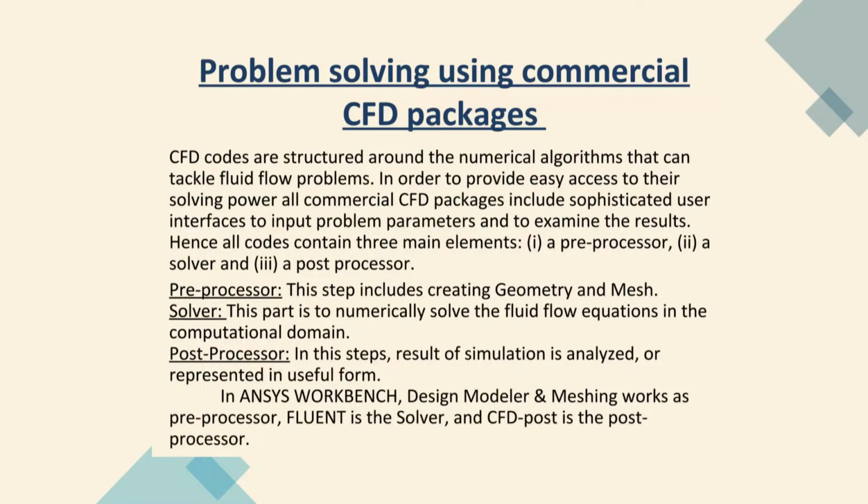The preprocessor step includes creating the geometry and the mesh. You can create the geometry and mesh somewhere else, export the mesh, and put it in the solver. The solver part numerically solves the fluid flow equations in the computational domain. Now, in the post processor step, the results of the simulation are analyzed and represented in usual form. So, whichever way your manager or your supervisor wants, you can present the result that way. So, these are very nice tools.